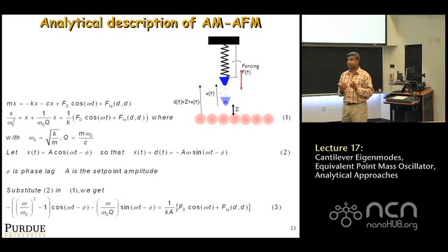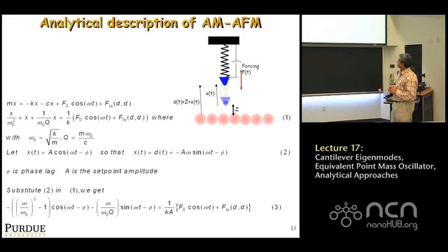And so as soon as you have a tip sample interaction force that depends on the rate of indentation, it means it's a rate dependent interaction law, which could come from viscoelasticity, it could come from plasticity, all sorts of sources. Okay, so this is our equation. How are we going to use simple analytical understanding to get to phase contrast?